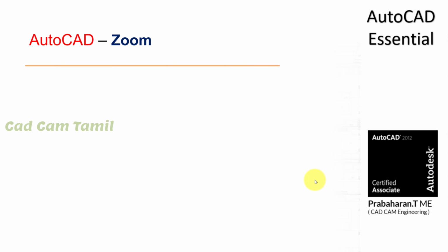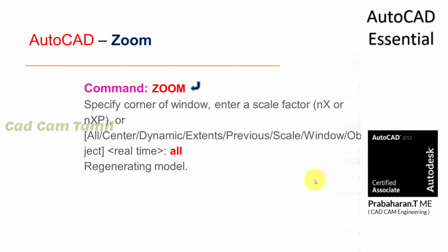Once you give the limits command, immediately we have to go for zoom. Okay. So once you enter the zoom command, plenty of options will come. We will choose only the first option called ALL, all. That means whatever size we have chosen is going to be zoomed on the screen now. Just give all, enter. So now your paper size is set on the screen. Otherwise, it will not be set. Until you give the zoom command, the size will not be applied to the screen.